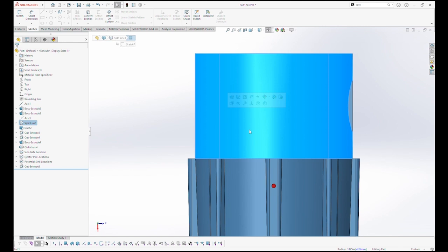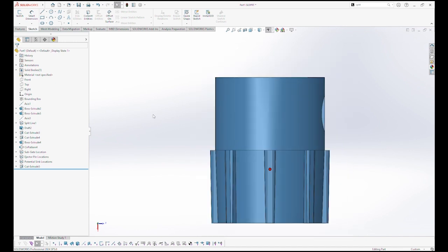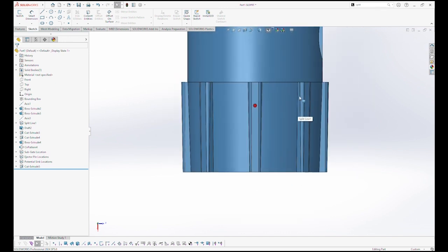And if you've ever tried to take two 5-gallon buckets apart and they've kind of vacuum locked on you, you know that that's a pretty impossible situation. It takes a lot of force to get some air in there to break that and to finally get those buckets apart. Same thing happens with your injection molded parts. If you don't put draft on them, it becomes a much higher level of force required to push the parts out. And when you're using ejector pins and you're pushing really hard, oftentimes you can misform or warp the parts as they're still a little bit warm. They're not 100% cooled.